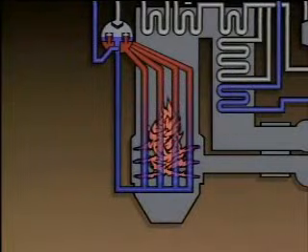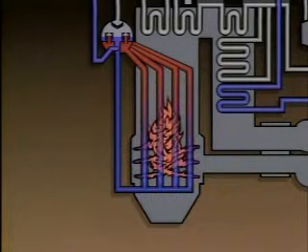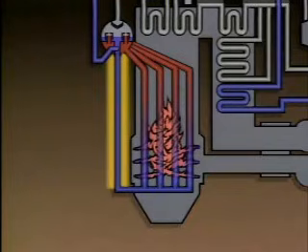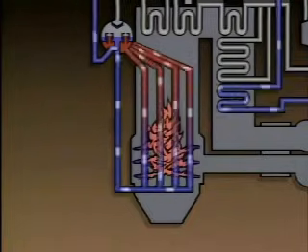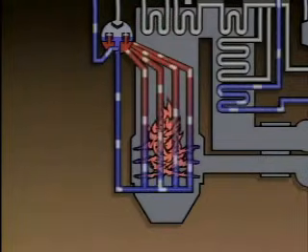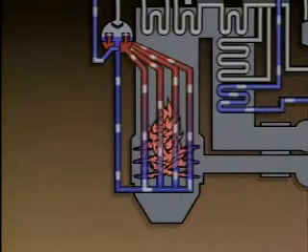The flow of water through some boilers occurs by means of natural circulation. The key to understanding natural circulation is the fact that cold water is heavier, or denser, than hot water or steam. In a boiler, the mixture of water and steam in the water walls is hotter than the water flowing from the drum through the downcomers. This is because the water walls are heated by the burning fuel in the boiler furnace. As the mixture of water and steam rises, cooler water from the downcomers flows into the lower headers and then into the water walls. The cooler water is also heated and rises, creating a self-sustaining flow through the water side of the boiler.